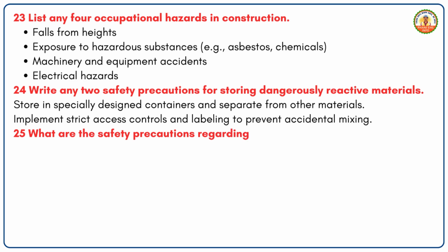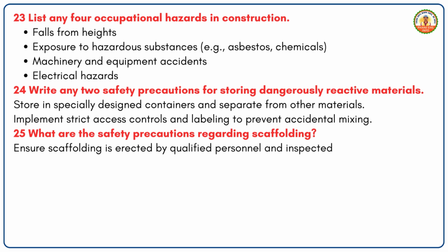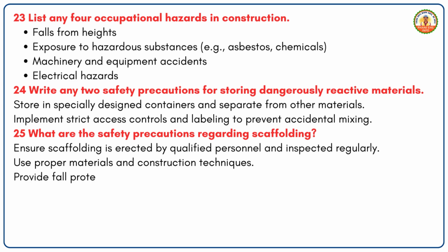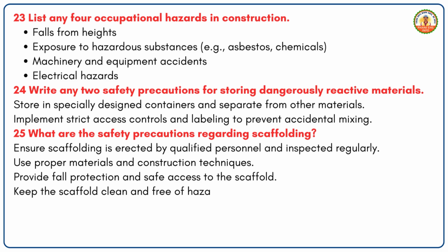25. What are the safety precautions regarding scaffolding? Ensure scaffolding is erected by qualified personnel and inspected regularly. Use proper materials and construction techniques. Provide fall protection and safe access to the scaffold. Keep the scaffold clean and free of hazards.